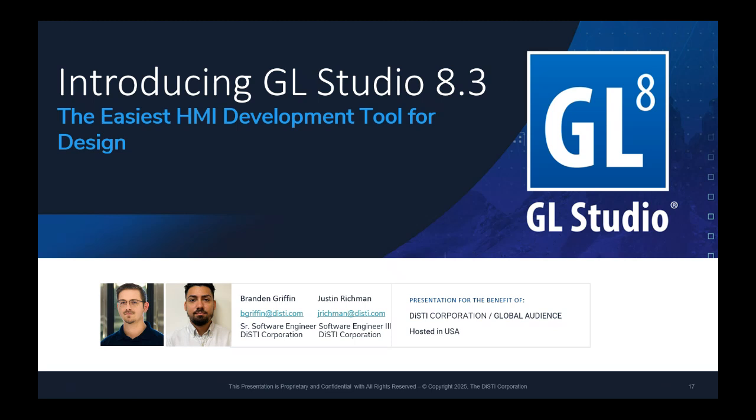First question is, if I have a GLS project in 8.2, how do I upgrade it to 8.3? So that should actually be a smooth process. You would simply open the 8.2 project in 8.3, and then it will prompt you to update the GLS file when you go to save.